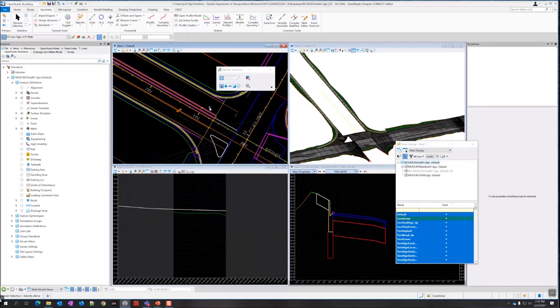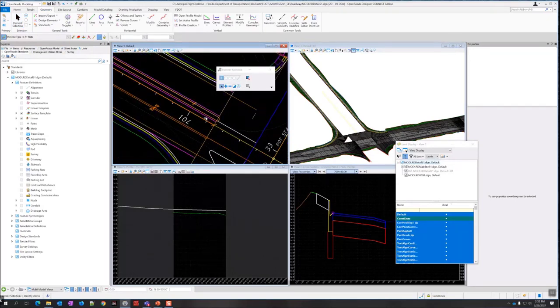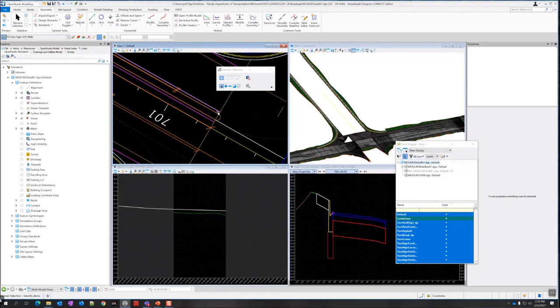Well, traffic separator lines, you can have it on a construction element, but in this case I just had the same feature definition. So now I should be able to build that civil cell using those lines instead of the reference.